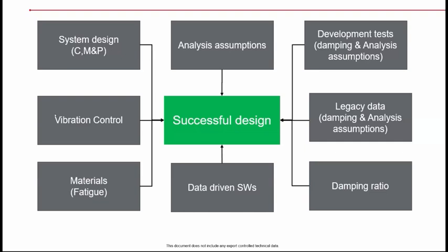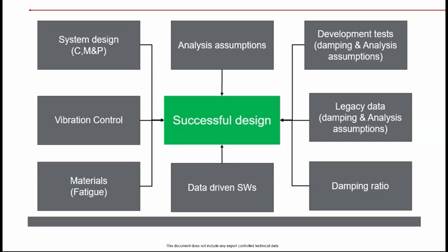Okay, and the vibration control aspects that we discussed, the three different ways of mitigating the vibration, that is isolation or system design itself, or the vibration absorption by inducing damping to the system. So with all these options explored well, and having a thorough understanding of all these aspects, will make us have a robust solution against vibration problems. And not only that, the key takeaway here is it's an integrated approach. Design for vibration is an integrated approach.